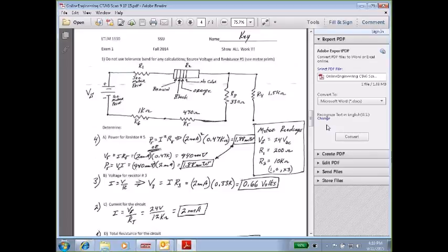Notice resistor number 4. Resistor number 4 is just a tongue hanging in the wind there, just flapping in the wind, not connected to anything. So if there is no current path, that means there's no current through it, therefore there'll be no voltage drop across it, so analytically we can ignore that one. We don't count that in the circuit. And thus we start talking about what an open circuit is.